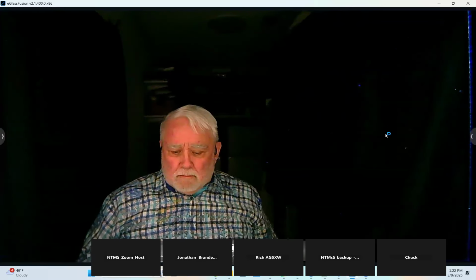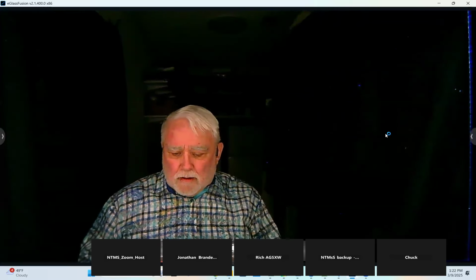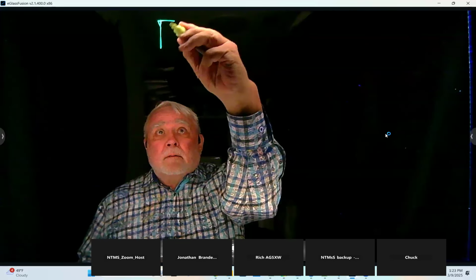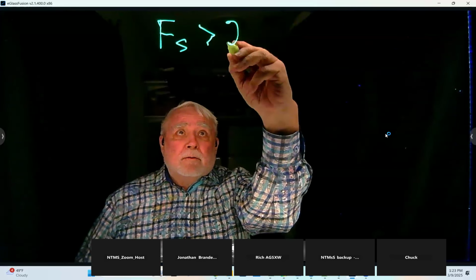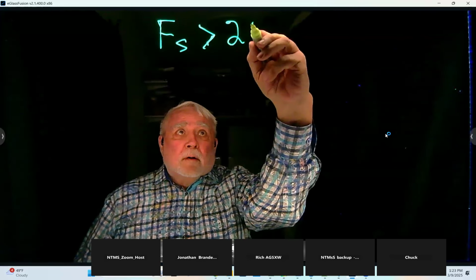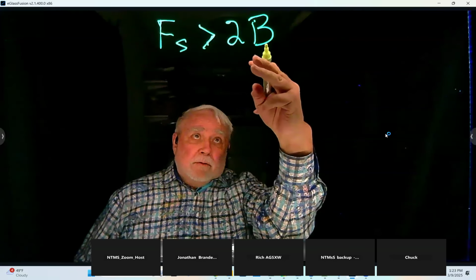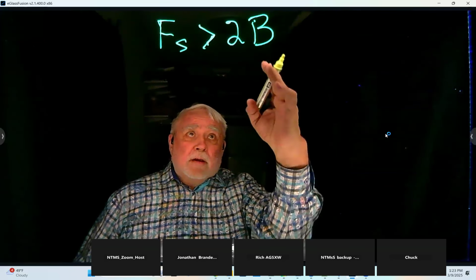So now we'll state the obvious here one more time for the Nyquist rate: a sample rate has to be greater than 2 times the bandwidth. And don't let that bandwidth confuse you. It's really 2 times the highest discrete frequency in the bandwidth.